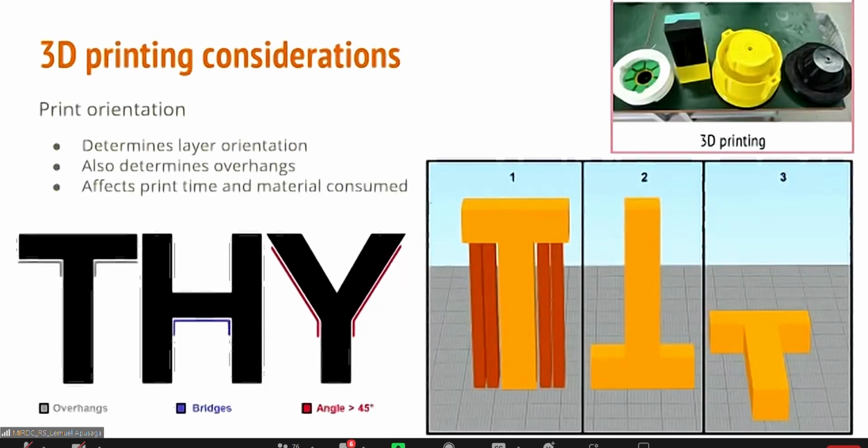You also need to consider the orientation. In 3D printing, there's something called printing supports. Since you're depositing layer by layer, if you have features like overhangs, you need support material because you can't print on air, right? For you to be able to deposit the plastic, there's something that needs to hold that overhanging part. So you will have support. Since one of the goals is to reduce the cost of making the pattern, you have to find the best configuration of the material such that there are minimal supports, because supports are going to be waste.